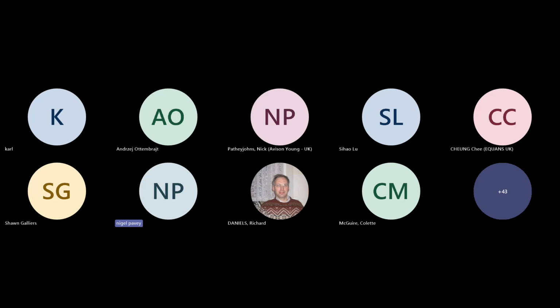Do you mean in an existing system? Yeah, so on an existing system, for instance, we get heavy scale build up and biofilm build up on an outlet. To manage the outlet itself, say for instance we put a new outlet on, replacing the tap, etc., but we nano coat that with like a graphene coating. Because graphene doesn't bond with biofilm, so it's a very smooth surface.